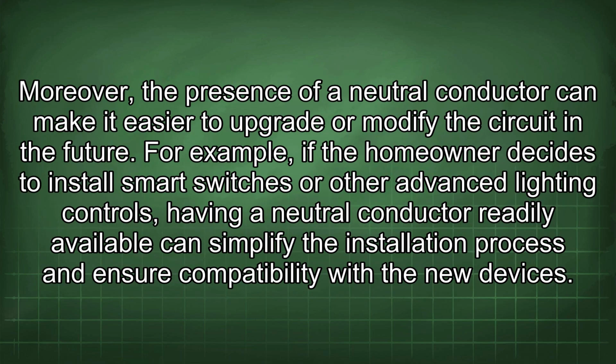Moreover, the presence of a neutral conductor can make it easier to upgrade or modify the circuit in the future. For example, if the homeowner decides to install smart switches or other advanced lighting controls, having a neutral conductor readily available can simplify the installation process and ensure compatibility with the new devices.